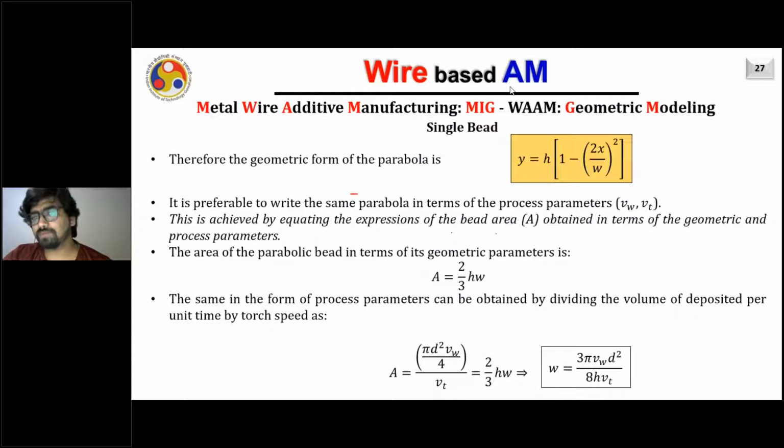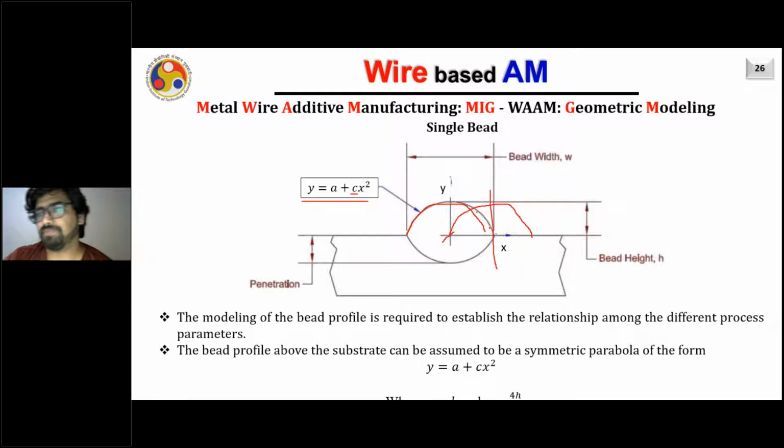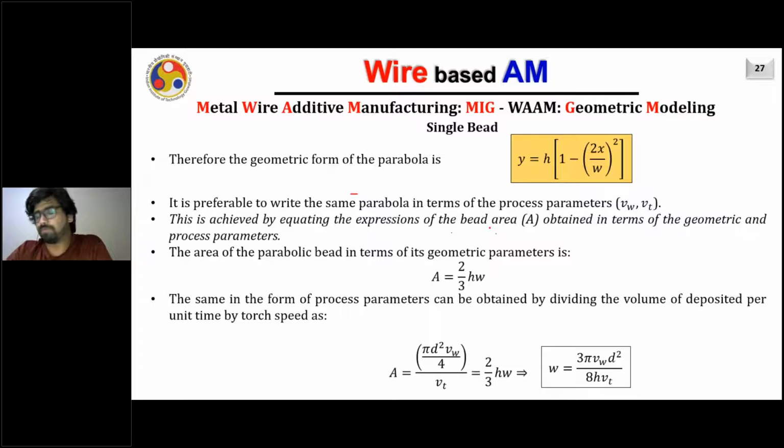Okay, there is a question from Shweta Ansari. No, it is not necessary that your bead will always be parabolic. It's an assumption, but why I'm doing it, you will appreciate immediately. You can even consider it circular, and the method of obtaining the distance between two consecutive beads will remain the same. That I can assure you. You can even fit a non-linear polynomial into that. There is no need to have only the parabolic or conic shapes. It can be any polynomial also.